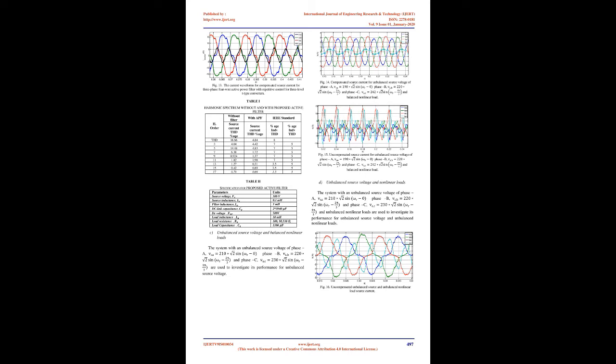The inner controller is designed for a phase margin of 74.7 degrees and bandwidth of 6280 rad/sec as depicted in Fig 3. The closed-loop system without the repetitive controller G0(z) is stable, where, 8. The sensitivity function of the closed-loop system with RC is expressed as, 9.